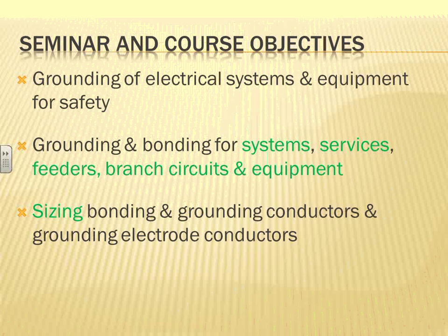And if you decide to use an ungrounded system for reliability, what do you do? You take a delta-delta transformer, separate from your system, and you run the assembly line on a delta-delta, if that's the situation.